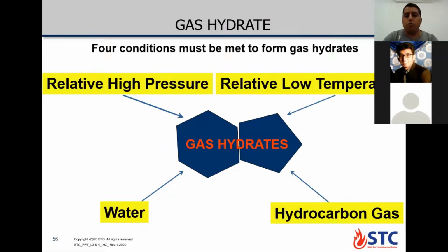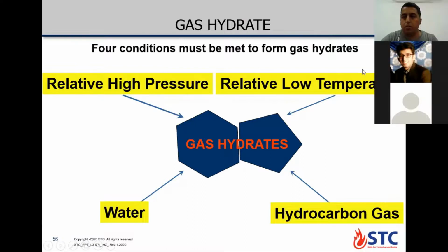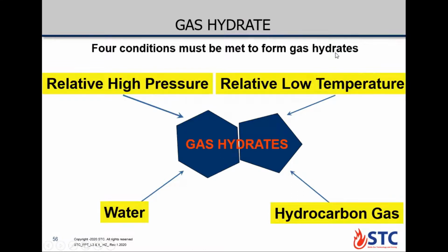Okay. After that, we'll talk about gas hydrates. What is a gas hydrate? What do you know about gas hydrates? It's something like the formation of solids due to the pressure difference. Okay. In which condition can gas hydrate form? Like if we have a choke, a point across which we have a high pressure drop, then the side with the lower pressure would have the gas hydrates.